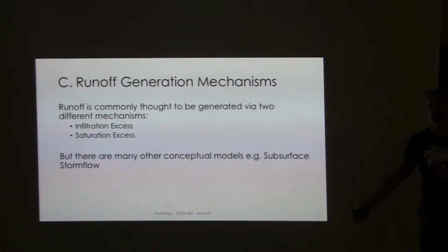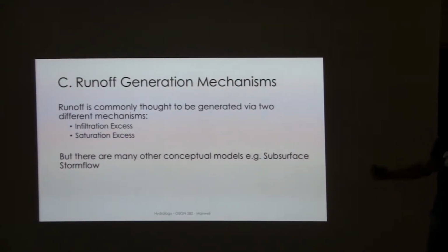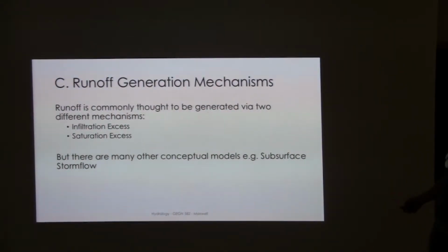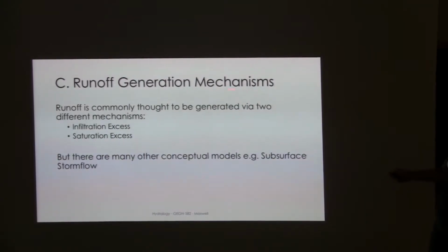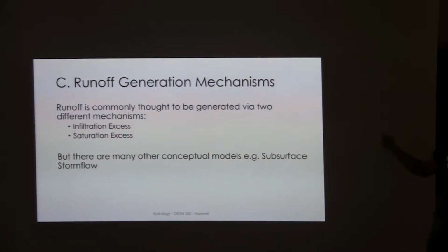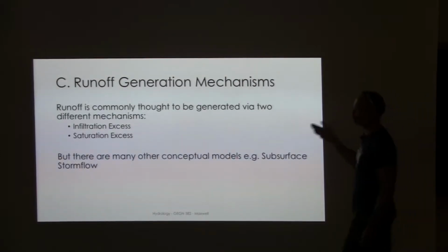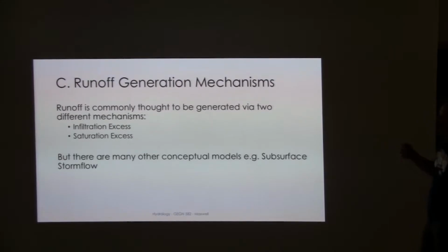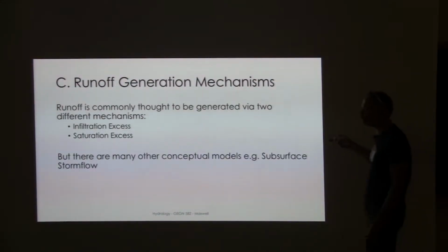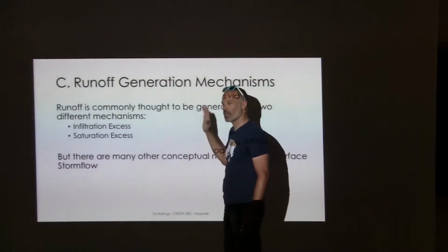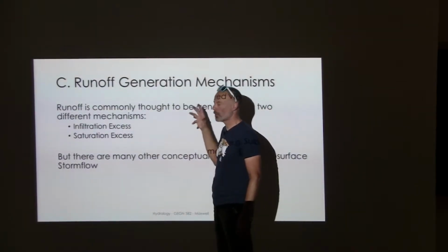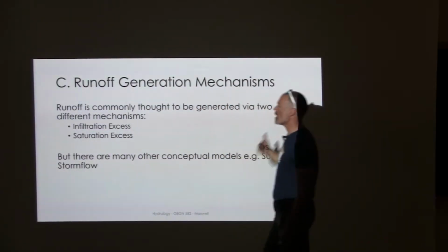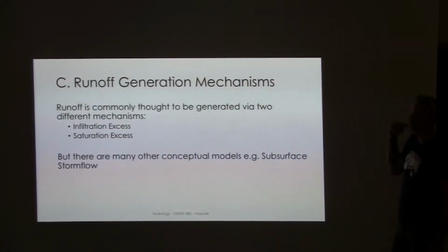So we bring this back to thinking about runoff and scaling runoff. We typically think of runoff by two mechanisms: infiltration excess, which we just talked about, right? Precip is greater than our Ksat, water ponds up, and we generate runoff. And then saturation excess, often called Dunnian flow; infiltration excess is often called Hortonian flow, although it has been said many times in the literature, Horton was not strictly Hortonian. Saturation excess, or Dunn flow, the water table is involved.